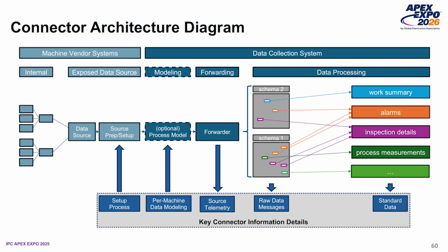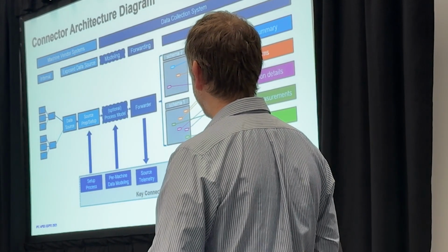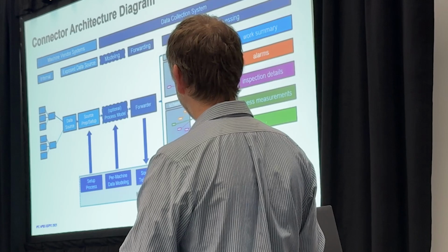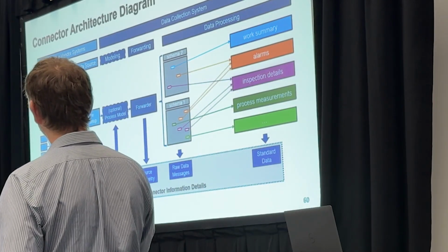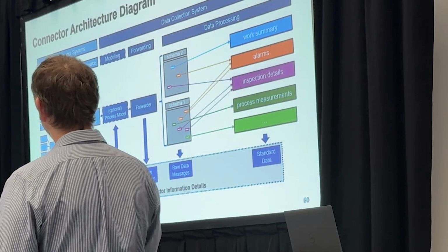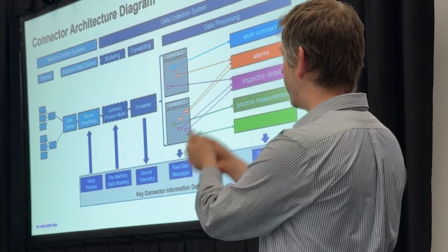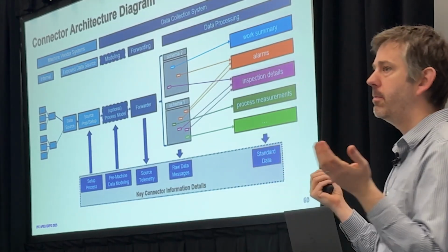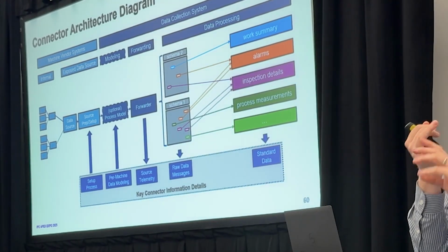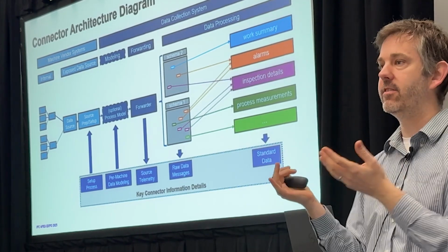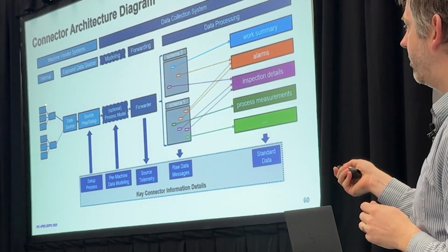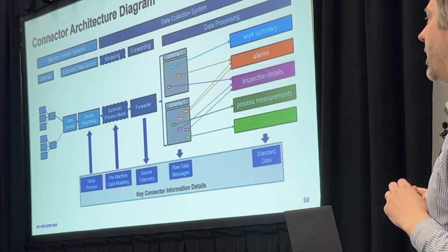And then on this block 2 and block 4, what it ultimately tends to look like is something like this. This is how we tend to see these data systems structured, which is, okay, I've got a bunch of systems over here. Maybe there's a bunch of internal links, but there's something I'm connecting to. So this might be the individual machine, connecting directly to this particular place and pulling its files. It might be that I've got a SCADA system. Someone bought Ignition or some other SCADA system in their factory, and so I've actually got a bunch of systems already pre-wired and I've got some OPC UA tags.